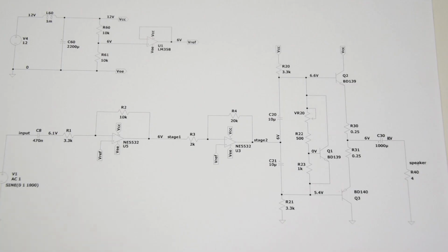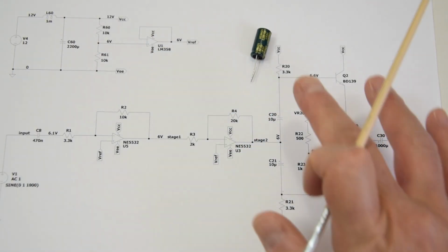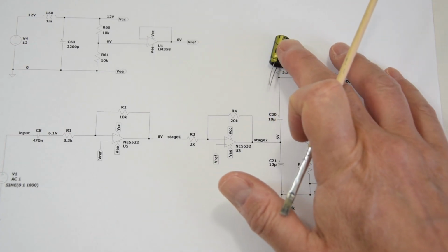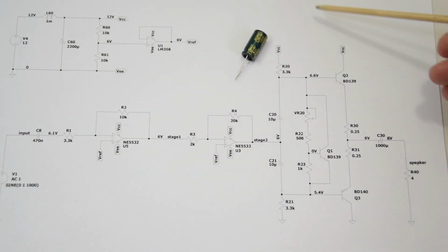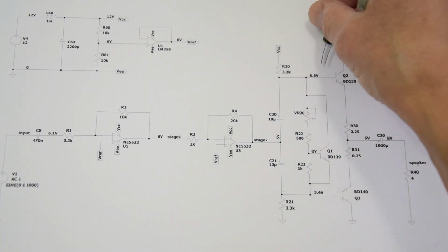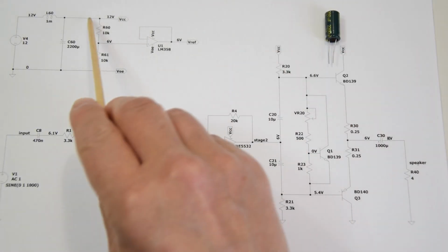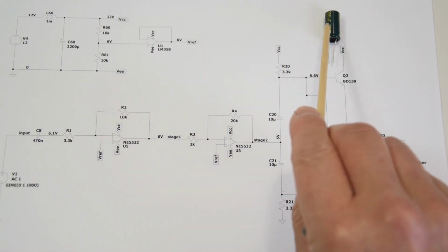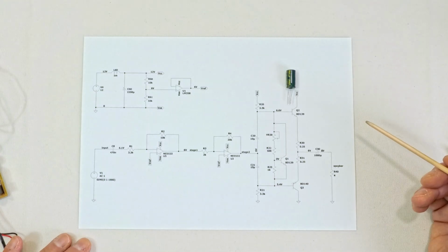Fortunately, there is a solution by placing an extra capacitor in the power rail. A capacitor can be seen as a small local power supply, like a battery. It can accommodate large swings in the AC signal in the output stage by delivering the current when needed instantly, when the power supply is not able to react that quickly. Let's try it on the breadboard and see how this works out.